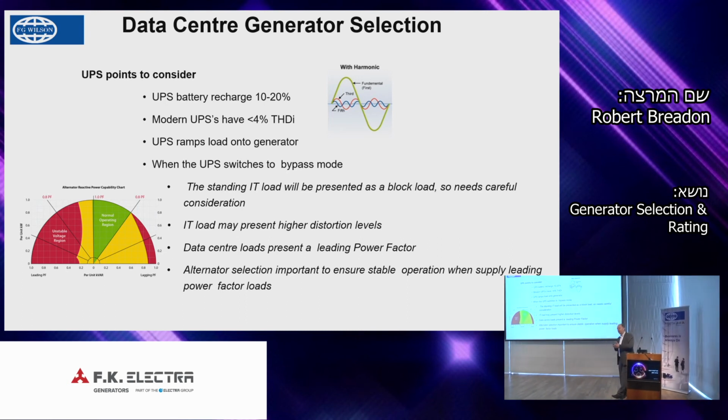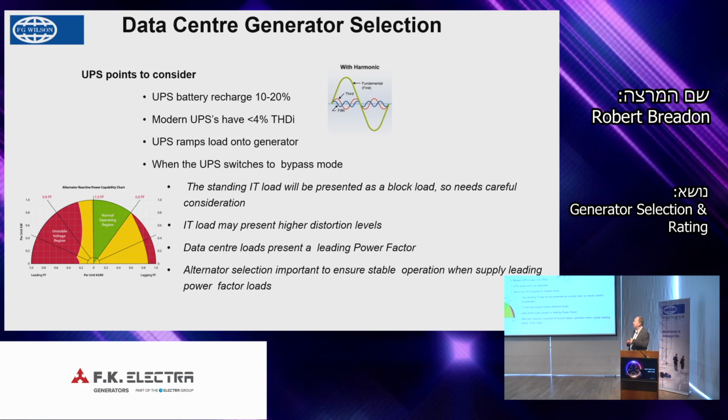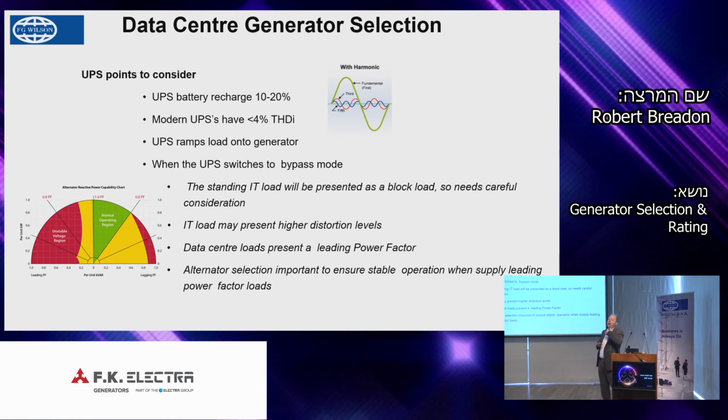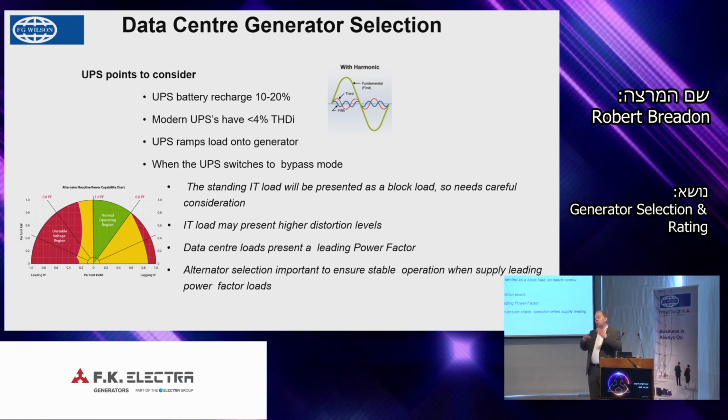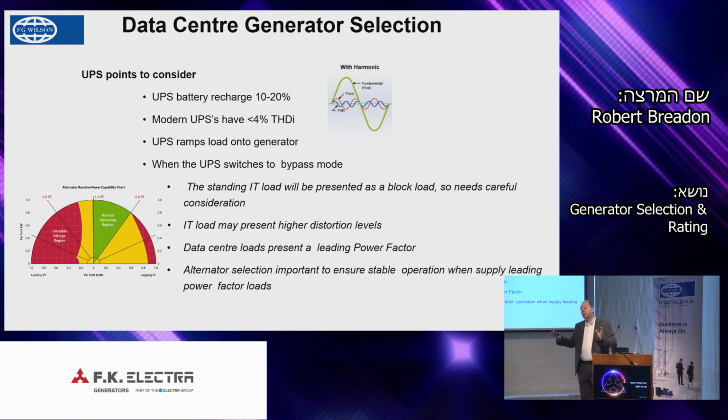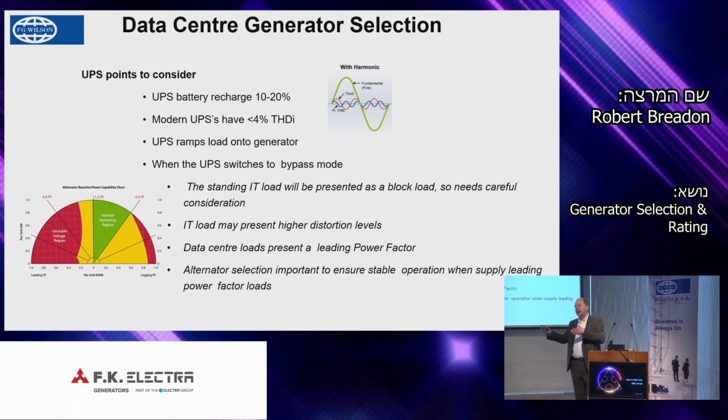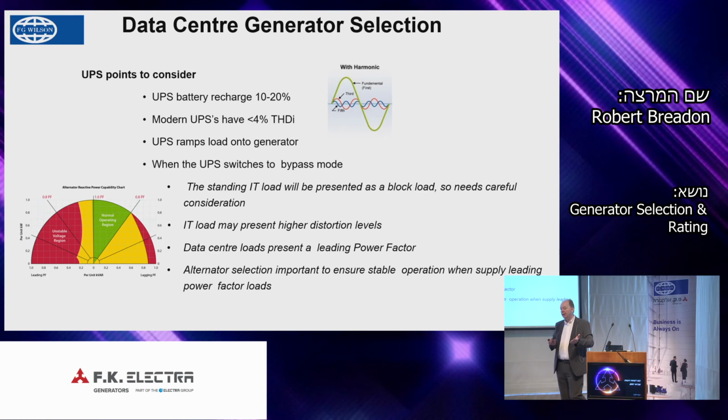In our selection software, we can have either a certain level of recharge or no recharge, because some customers say it's a standby environment, your genset's going to be on for half an hour, we'll go back to mains, and the mains will recharge the batteries. And customers do look at it from that perspective.